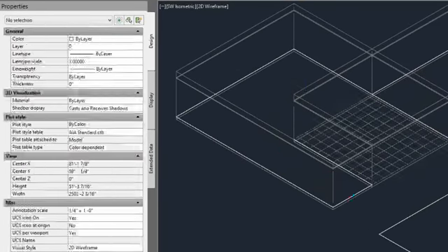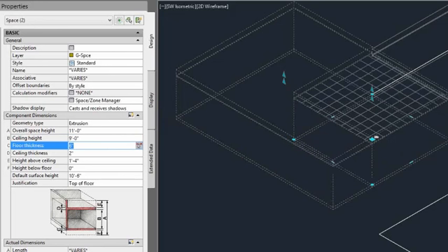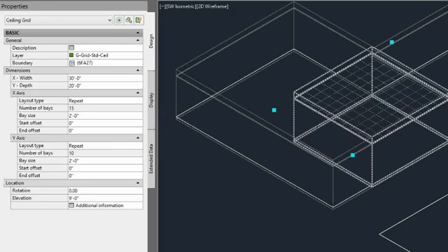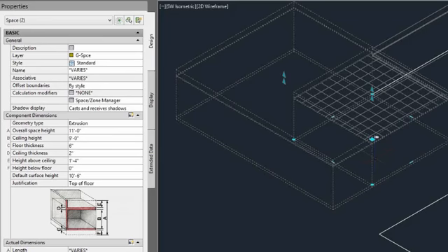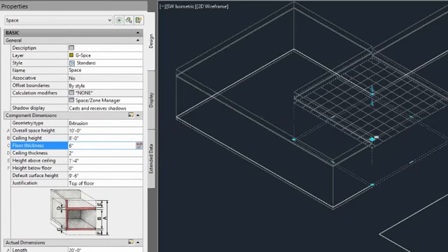If I go to a 3D view, I can see that it did not snap to the ceiling elevation, but if I look at the ceiling elevation and hit 9 feet, it did pop up there that time. So when I placed it, it didn't actually place at the ceiling like it should have. That was probably something that I did wrong. But if you notice, I come back here and change to 8 feet, that grid will pop up and down exactly where it needs to go.